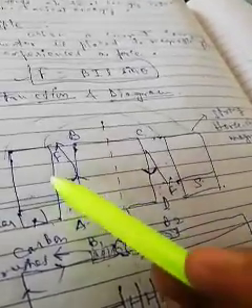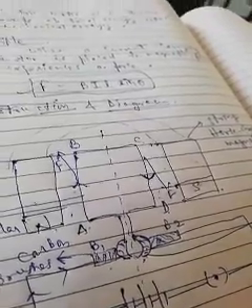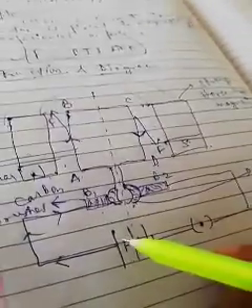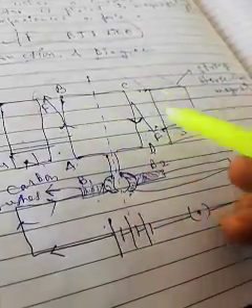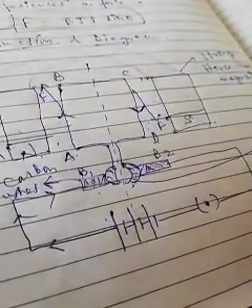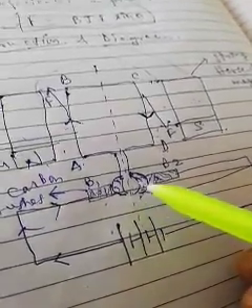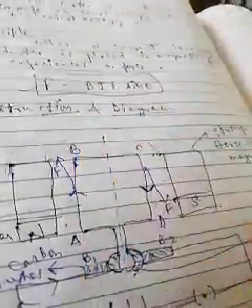The role of the carbon brushes, the split ring commutator, and the strong magnetic field are all important to understand. Why carbon brushes? Carbon brushes make the contact between the battery terminals and the ends of the coil through the split ring commutator. The use of the split ring commutator is to reverse the direction of current so that the coil rotates every time with the same sense of rotation.